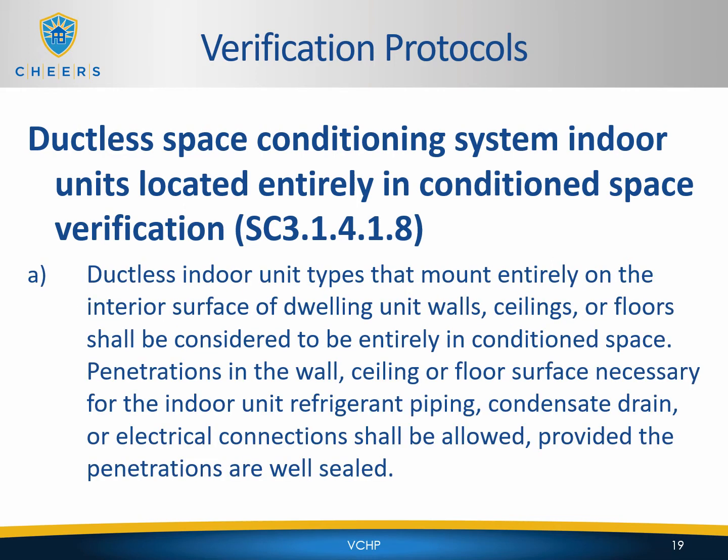Ductless indoor unit types that mount entirely on the interior surface of the dwelling unit walls, ceilings, or floors shall be considered to be entirely in conditioned space. Penetrations in the wall, ceiling, or floor surface necessary for the indoor unit refrigerant piping, condensate drain, or electrical connections shall be allowed, provided the penetrations are well sealed.